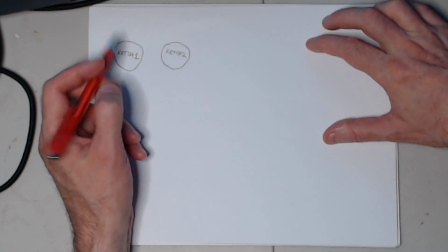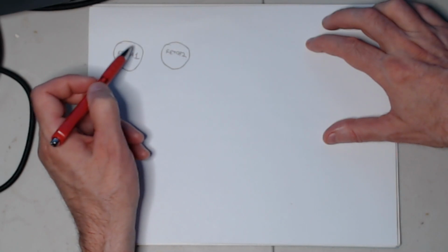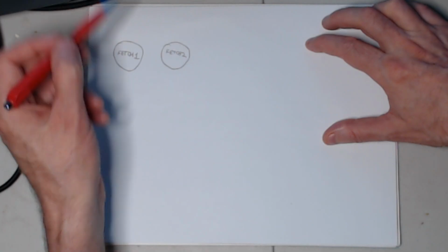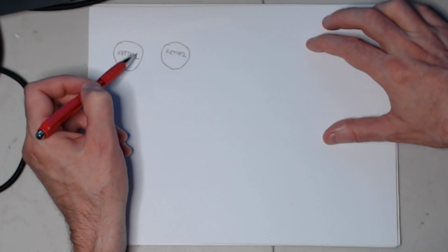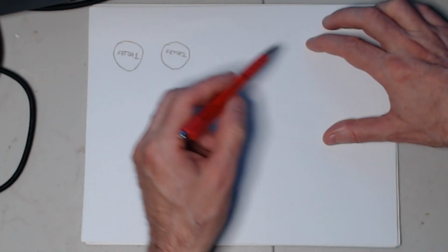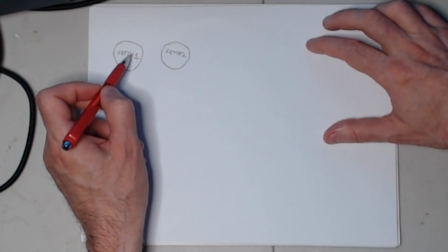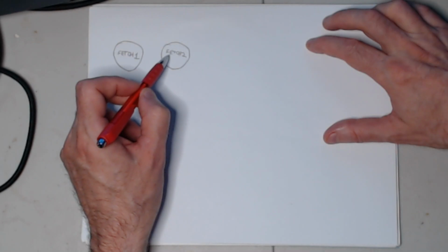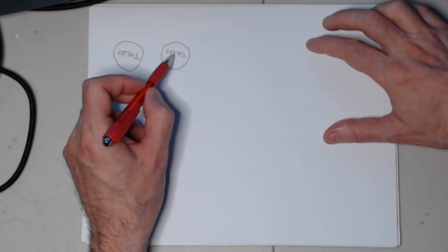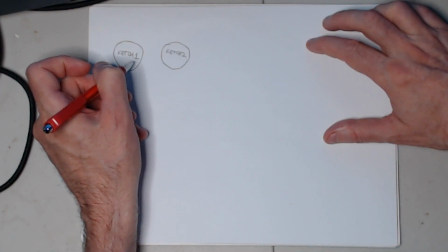The Q output goes to an LED on the front panel that says this flip-flop is on. For each of the various states, we're going to do the other states eventually, there's an LED that lights up when each state flip-flop is on. So it'll tell you which state it is.